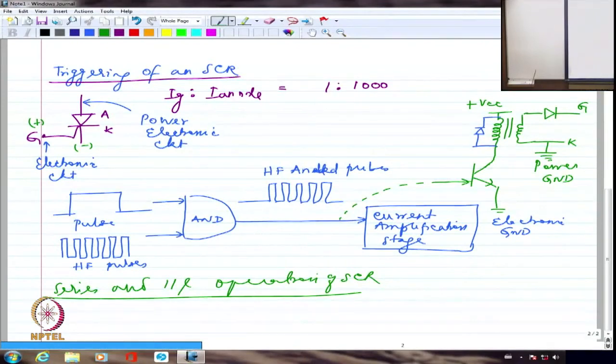See, you are doing power amplification. This is even a power amplifier. I should not say only current amplification. It is actually a power amplifier. Because what I get from here may be 5 volts, and what I get from here may be 15 volts. And what I get from here may be milliamperes or microamperes, but what I get from here will be of the order of amperes. So I'm not only amplifying the current, I'm also amplifying the overall power. And for that I'm drawing the power from VCC. So VCC is supplying the power for me to amplify the current pulse.